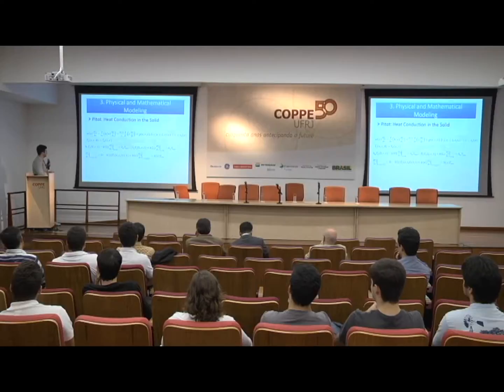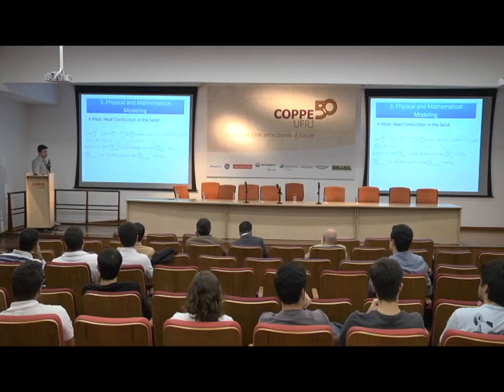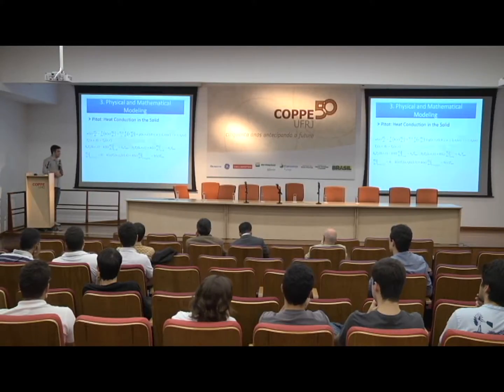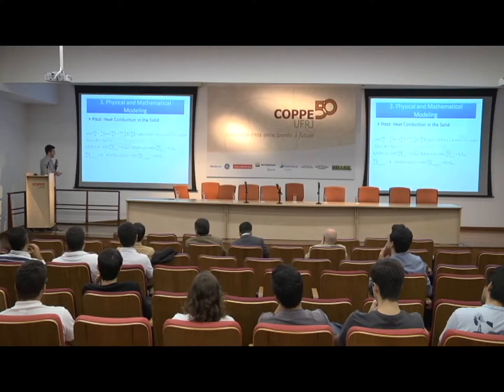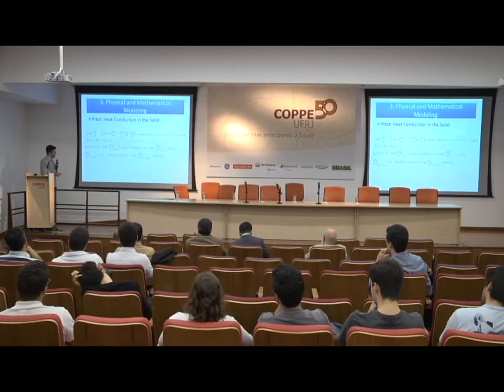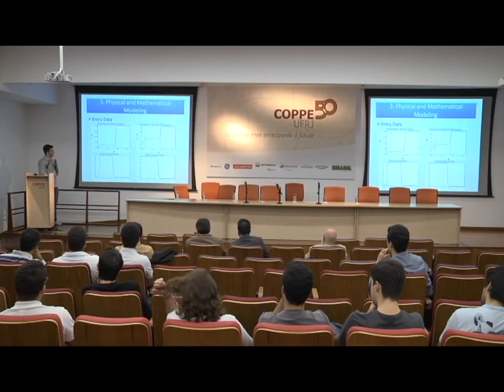At the stagnation point, we used a heat transfer coefficient from the literature, correlations basically, and for the coupling between the solid and the fluid, it was used this H here, this heat transfer coefficient that will be calculated iteratively between the fluid and the solid, that I will explain a little bit more later.